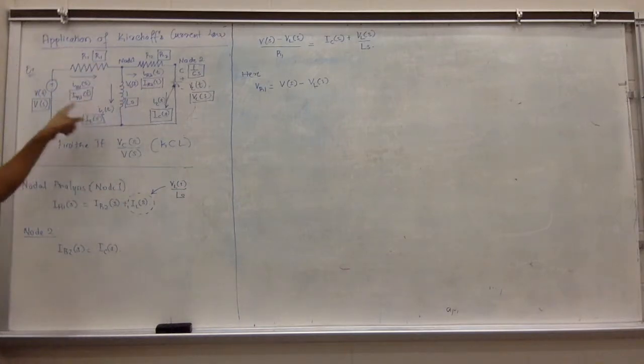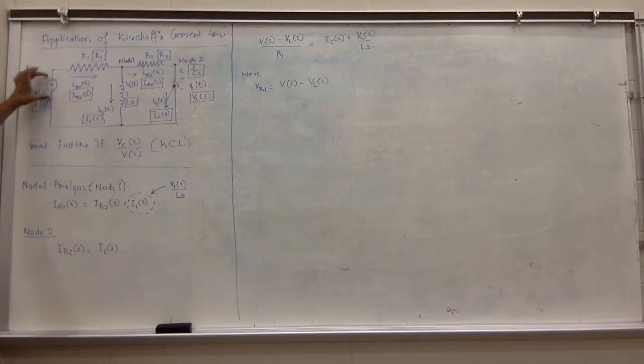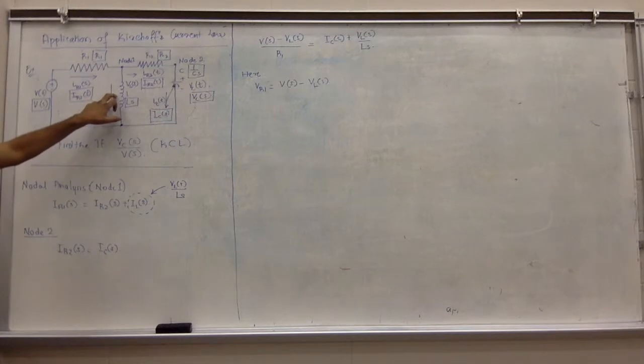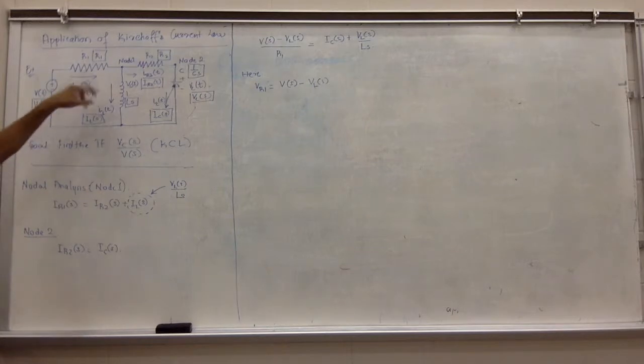What happens is, when you have a circuit and voltage applied, it gets split into this and this. How do you apply Kirchhoff's voltage law to this first mesh? Voltage around the loop is equal to 0.